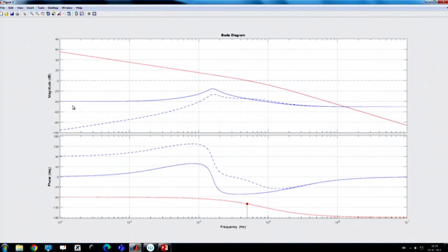But in closed loop we can reduce the low frequency output impedance, so that we can make the converter, that means if it is a voltage source, we are trying to achieve a very low DC output impedance, so that it has almost nearly perfect voltage regulation for the entire nominal load range. But at high frequency, that ESR effect cannot be avoided, that will create a jump. But this ringing effect is coming. So what can you do?